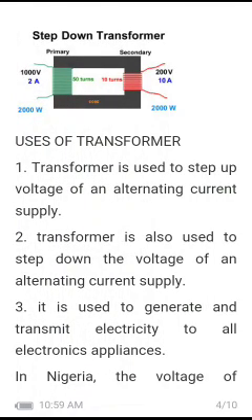Look at the diagram also. We have the 1000 volts. In blue color, we have the 2 ampere, that is the amount of current that flows in, and 2000 watts for the power. Look at the number of turns of coil, which is 50 turns. And look at the number of turns on the secondary coil, which is 10 turns. Then the voltage reduced from 1000 to 200. And we have an increase in current, which is 10 ampere from 2 ampere. The power rating remains the same.